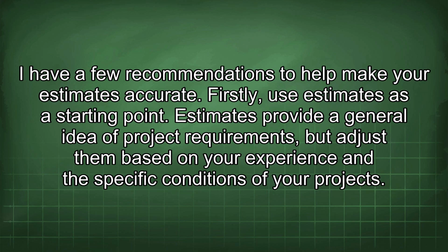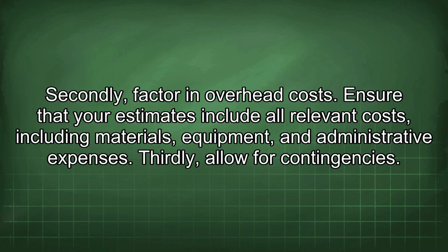I have a few recommendations to help make your estimates accurate. Firstly, use estimates as a starting point. Estimates provide a general idea of project requirements, but adjust them based on your experience and the specific conditions of your projects. Secondly, factor in overhead costs. Ensure that your estimates include all relevant costs, including materials, equipment, and administrative expenses.